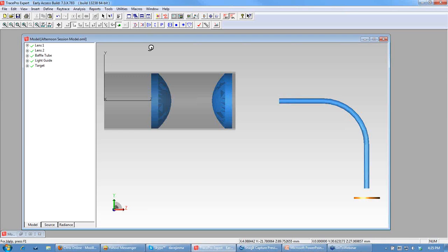What's nice about ray files is that they're based on measurements of the complete package, the complete LED in this case. So you don't need to build a model of the LED. Everything such as the epoxies, the coatings, the shape of the lens is all taken into account because they're measuring the finished product. So really you just need to insert that source into TracePro and not have to build any geometry. We did do one of our webinars about a year ago on accurate modeling of LEDs in TracePro. So if anybody's interested, if you go to that webinar section, you can download and see a more complete discussion of ray files, surface source properties, grid sources, and all the different ways you can model LEDs.